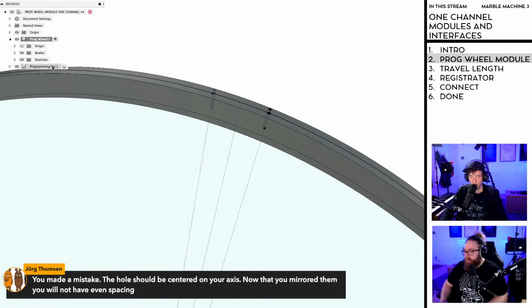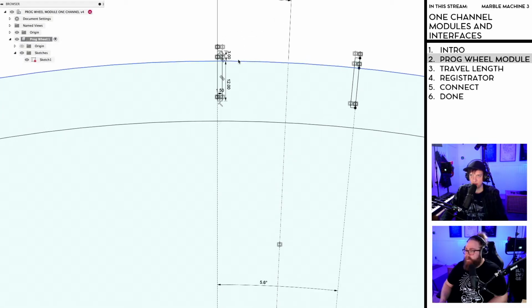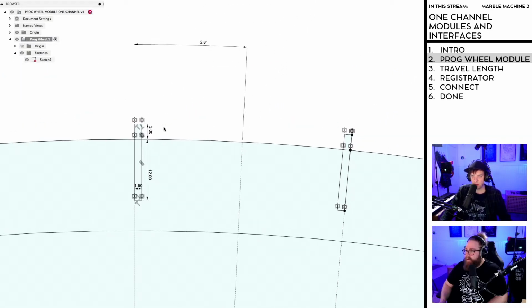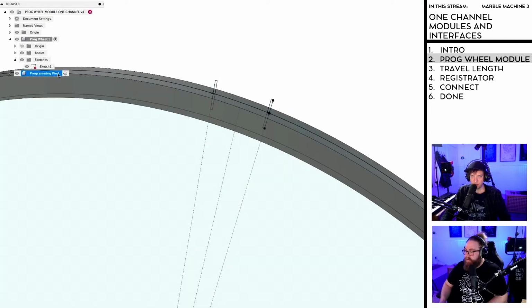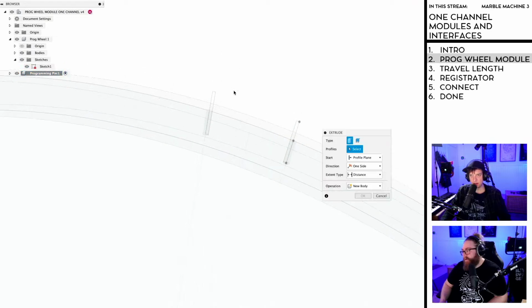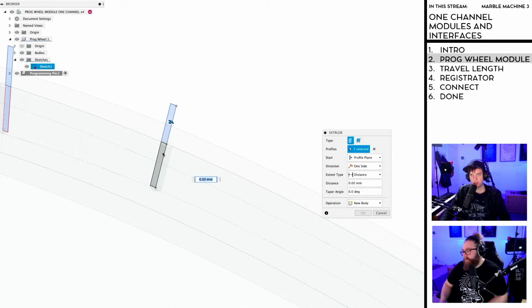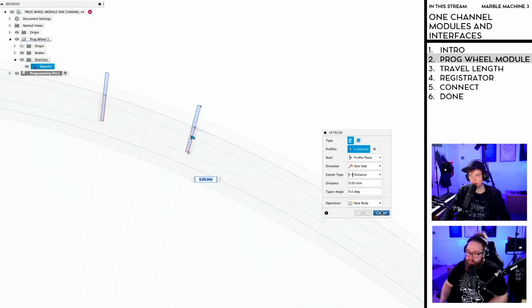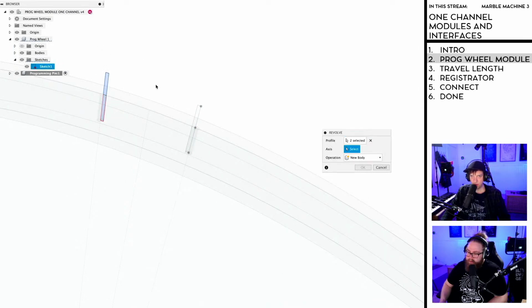And now when we started on that sketch, let's make the programming pin. And then it's so fun because then we can just use the same sketch. So for now, let's say it sticks up 10 millimeters. It's probably a little bit much. And now we can just use the same sketch to create our programming pins. We're not going to go into them now. Wait, this didn't work. Revolve. Like this.